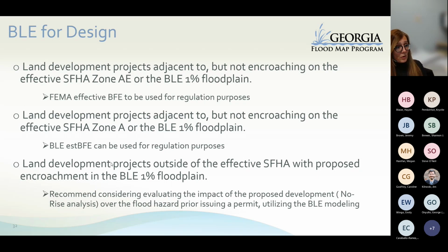If you have a proposed project which is adjacent to but not encroaching on the effective special flood hazard area zone A or the 1% BLE floodplain, in this particular case, the estimated BFE based on the base level engineering analysis can be used for regulation purposes. So if your effective special flood hazard area zone A does not have any information about the base flood elevation, the base level engineering analysis provides this information for you.